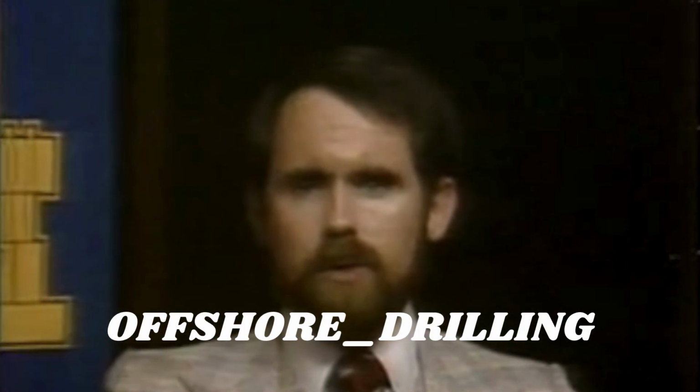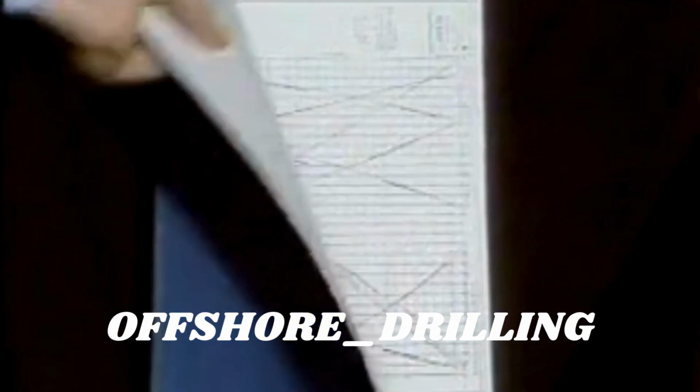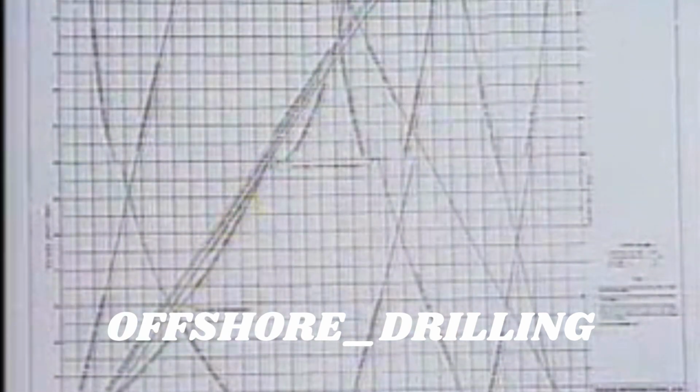Also, a new buoyancy force is set up which compensates for the additional moments. The ship trims about its tipping center, also called the center of flotation. The position of the tipping center changes for a given vessel with changes in draft, but the designer has made it easy for us to locate its position at any draft by use of the hydrostatic curves, which we discussed briefly in Part 1. A reproduction of the hydrostatic curves of the SEDCO 445 can be found on page 12 of your SEDCO self-study guide.